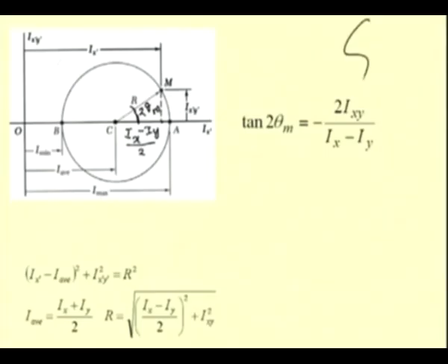That means, for any body, let us say if I take this body, if this is the original axis x and y, and these are the axes corresponding to the principal axes, then they are at 90 degrees to each other. So, let us say this is the axis corresponding to the maximum moment, then this corresponds to the minimum moment, the second moment, then they span 90 degrees.